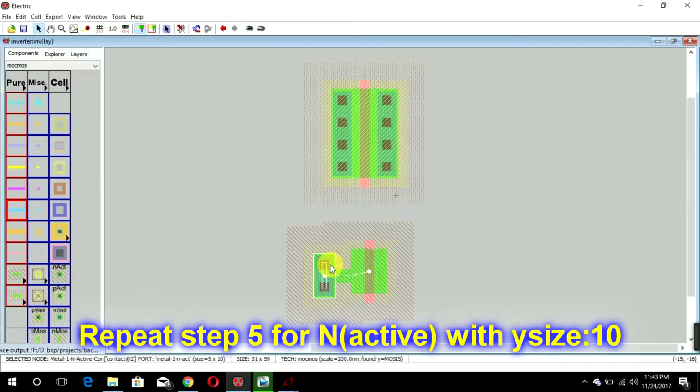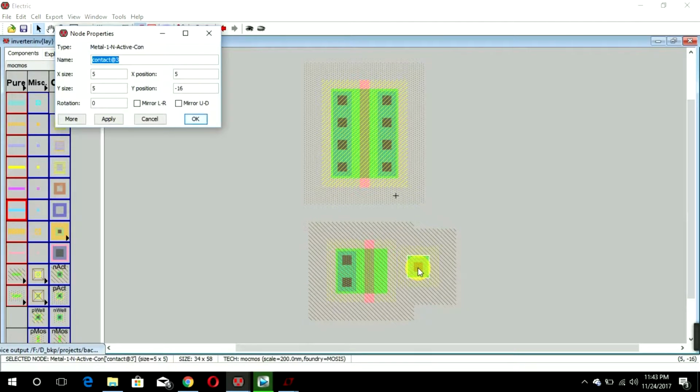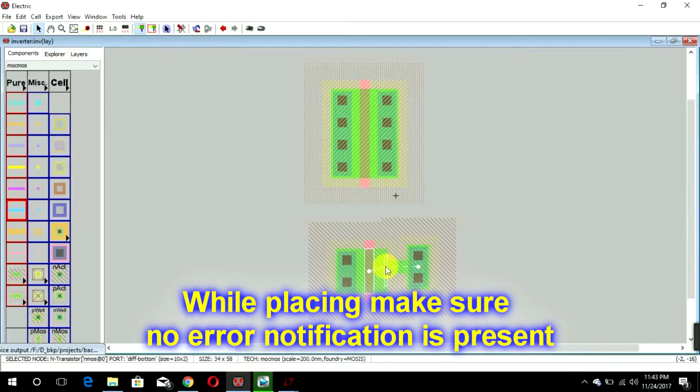Okay, we are making the connection as we had done in the schematic. It's the same way, left click and then right click, Ctrl+I, 10. Okay, so could you see this line coming up, and active spacing is 3.5. I'm keeping the space between this poly and active as 3.5.